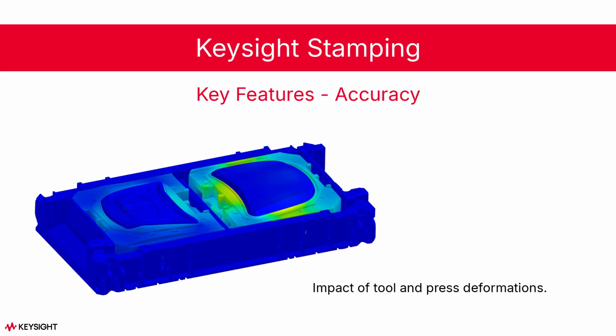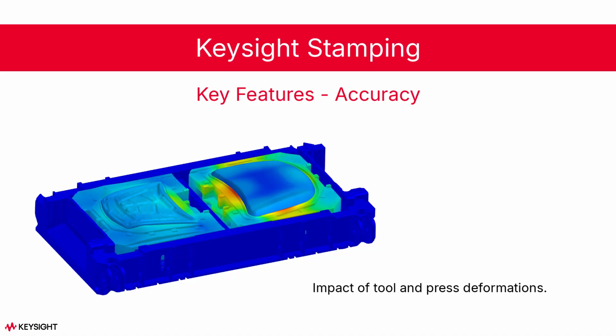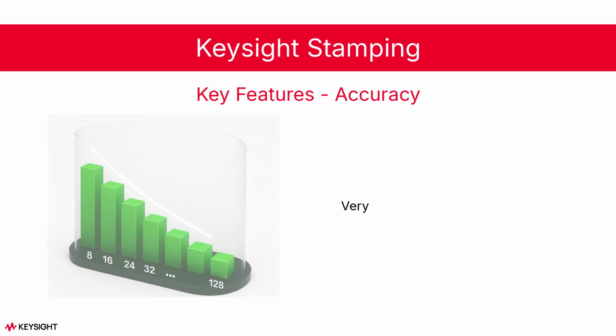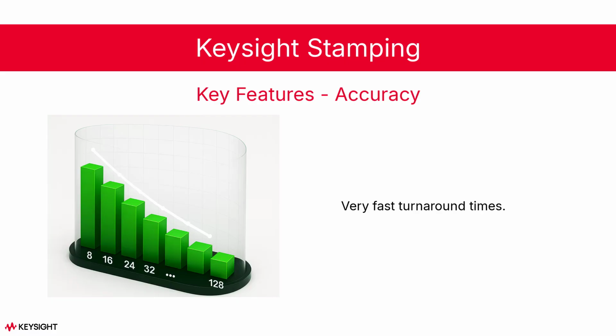Beyond standard stamping simulations, the full 3D models of tools and even presses can be incorporated, capturing their elastic deformations during stamping, which can potentially affect spring-back, draw-in, and even the aesthetic quality of the components. And thanks to excellent computational scaling, from desktop PCs to large clusters, you can run at least 2 full iterations per day, even for the most complex parts.